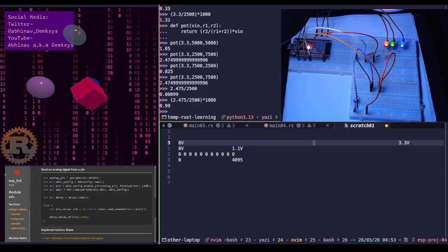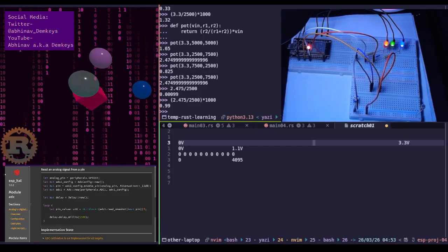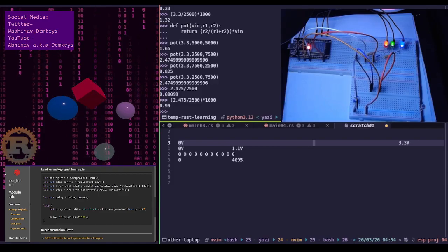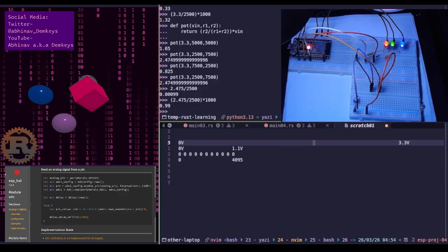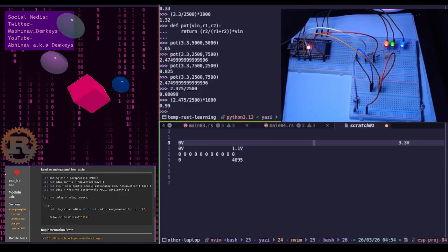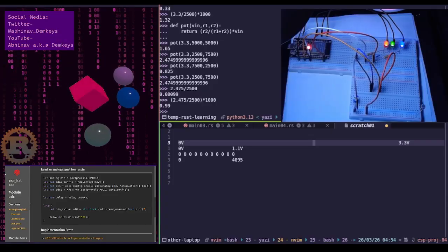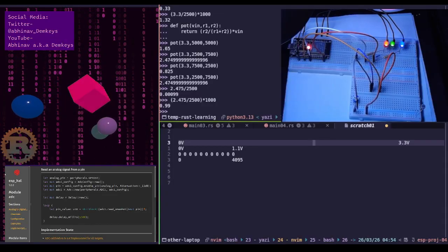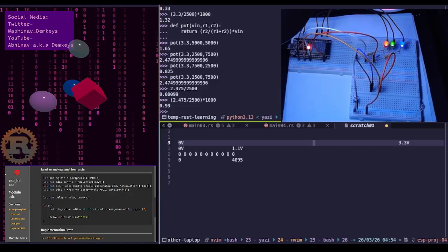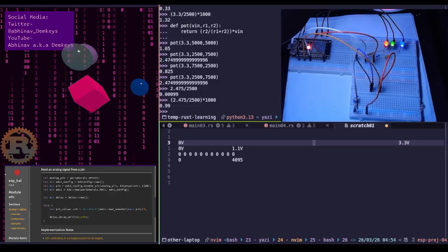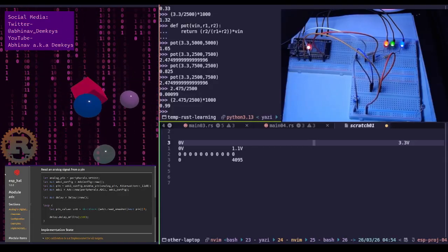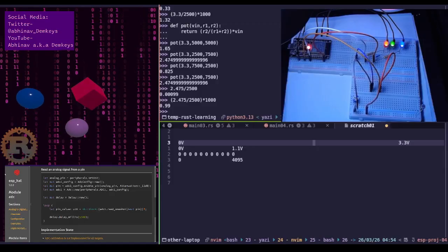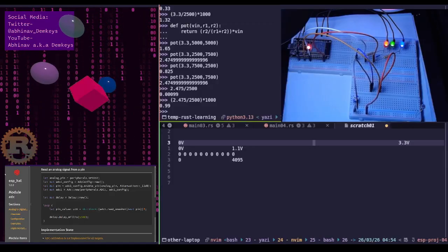That is 330 nanoamps. That's tiny. Okay. Because the pin's resistance is so much higher than the potentiometer's resistance, the ADC is invisible to the circuit. It doesn't load the circuit or pull enough current to change the voltage you're trying to measure.